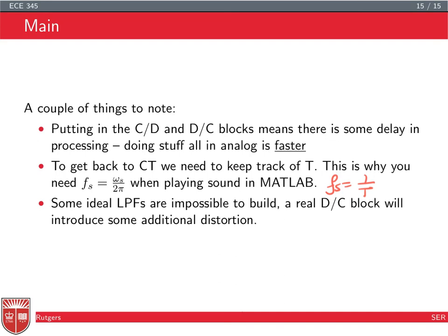So here I conclude the chapter on sampling. Again, the main concept is the sampling theorem, which says that if I have a signal that is bandwidth limited, meaning the maximum frequency is omega 0, then if I sample it at twice omega 0, I can recover the signal just from the sample points. From the discrete samples, I can recover the whole continuous time signal at any time. And this has huge impact on engineering applications.